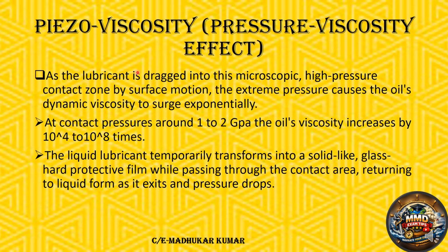And piezo viscosity, the pressure viscosity effect. What is this? As the lubricant is dragged in through the microscopic high pressure contact zone by surface motion, the extreme pressure causes the oil's dynamic viscosity to surge exponentially. So the dynamic viscosity of the oil changes, and due to the high pressure, it surges exponentially.